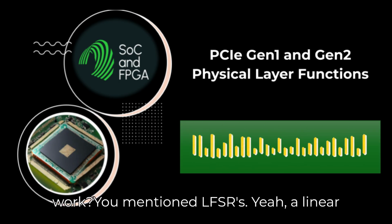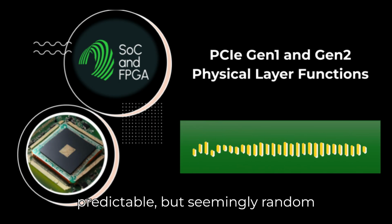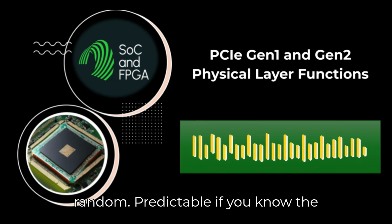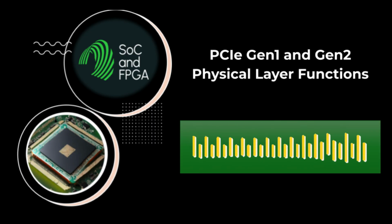How does it actually work? You mentioned LFSRs. Yeah, a linear feedback shift register. It's a digital circuit that generates a long, predictable, but seemingly random sequence of bits, a pseudo-random binary sequence, PRBS. Predictable, but random. Predictable if you know the starting state and the polynomial defining the feedback taps. But the sequence looks random statistically. Okay. So how is it used?